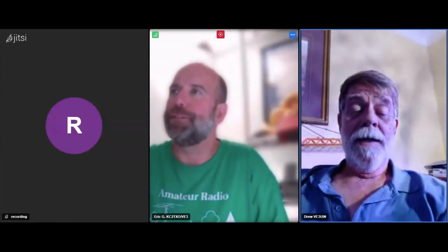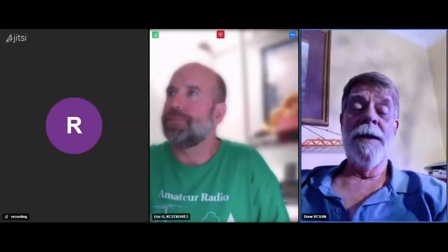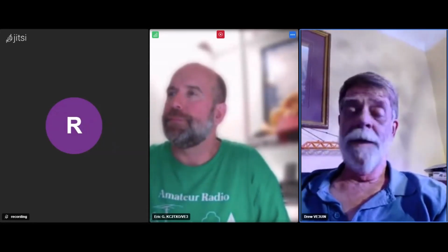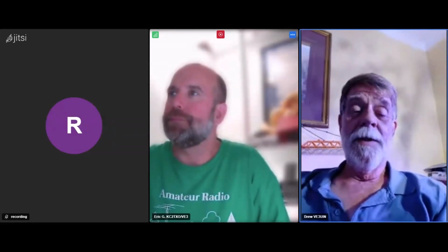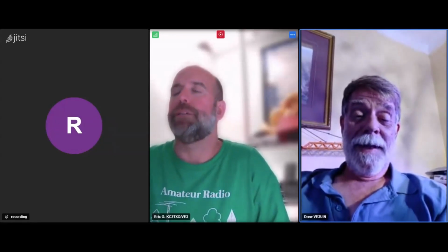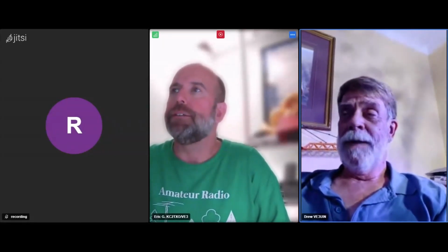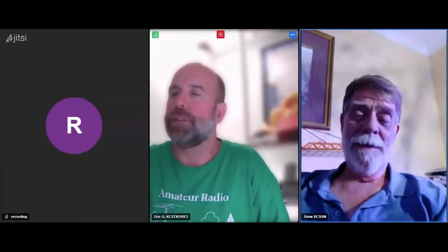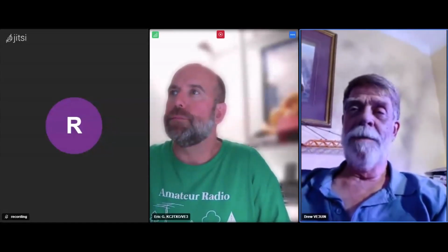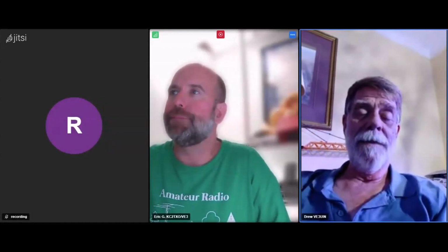So I can work 60 meters FT8, and I use my terminated end-fed, and it matches right to it. Bang, no problems. So that's the convenience of that design for me, is I don't have to worry about it. I just hook it up, and its match is going to be pretty well bang on.